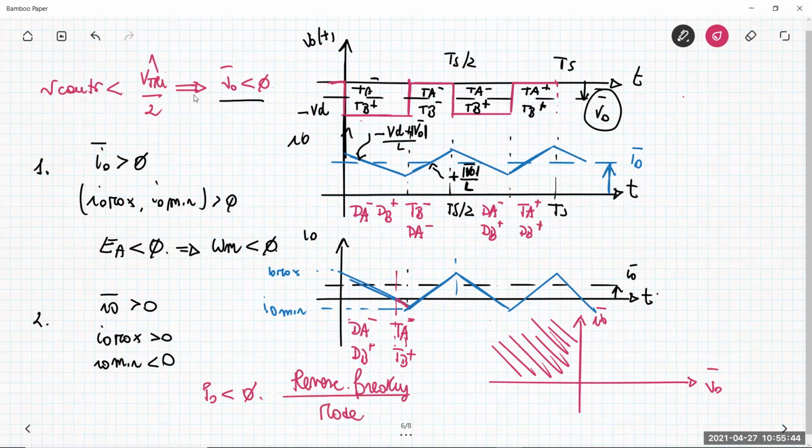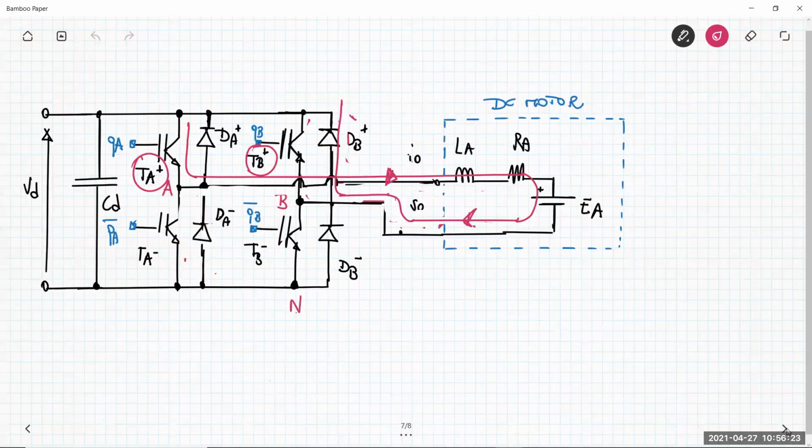So we have the motor rotating in the counterclockwise direction, for example. So the direction of rotation is inverted with respect to the previous case. And now we are absorbing power. The switching power pole is absorbing power from the motor. So we are decelerating the motor, okay? There are two other graphs that arise when you have negative voltage, and also negative average current.